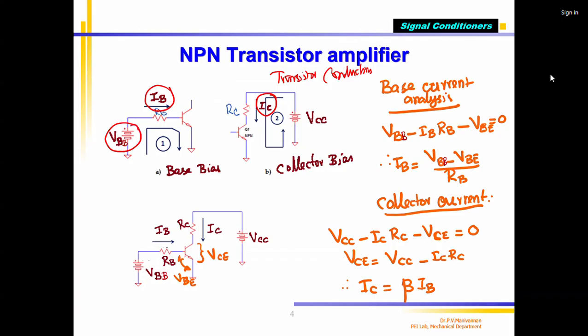Okay, so now, if I give, for example, VBB equal to 2 volts, what happened? VBB is 2 volts, and I know that my RB equals 1000 ohms. Already told yesterday. Now I can calculate IB equal to what? This is known, 1000 ohms. VBE equal to 0.7 volts.